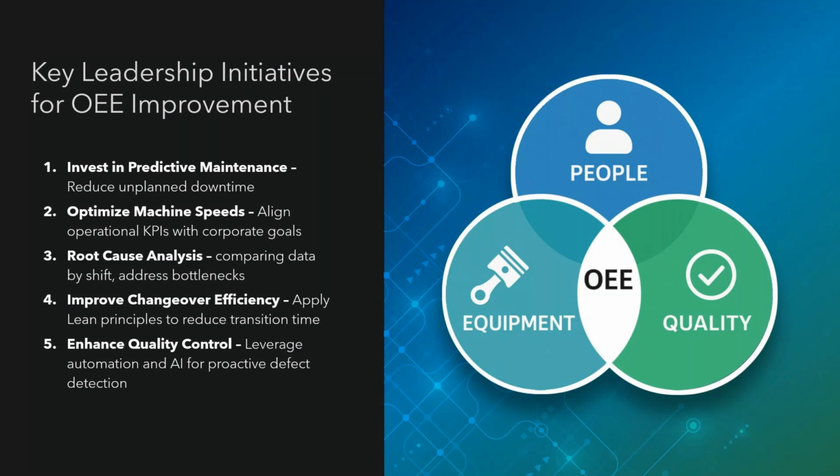So utilizing the Paretos that we've seen and some of the reason codes for that downtime, we can target when a machine may go down or when we should intervene on a maintenance aspect. We've always done preventative maintenance. We have standard maintenance rules for specific machines or cells, but this is a more dynamic way where we're consuming granular good data from a known source of truth, and we're implementing predictive maintenance for really reducing that unplanned downtime and avoiding the big hits that we see when equipment is down and not producing parts.